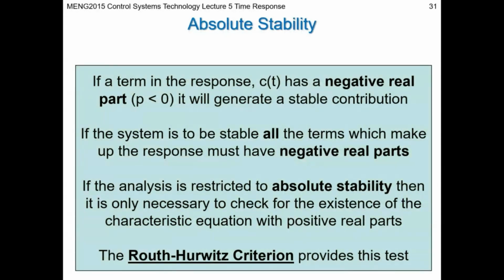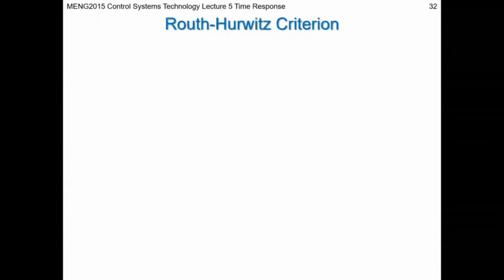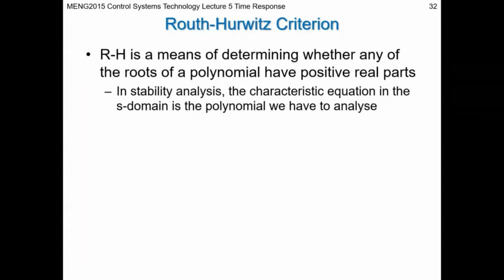And that's where this tool that I was coming to, Routh-Hurwitz, comes in. So let's have a look at Routh-Hurwitz. We use it as a tool in its own right, but also as a part of our process when we come to our next major tool, which is root locus. Root locus is called that because it looks at how the roots of the characteristic equation move when something in the transfer function is changed. And the thing you normally change in your transfer function is the control variables, right? The input from your control system.